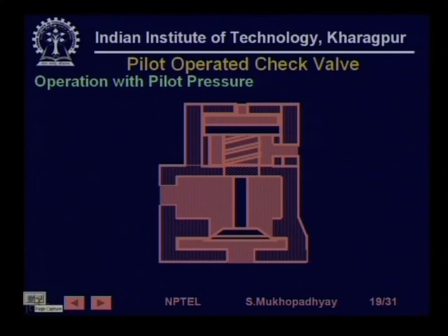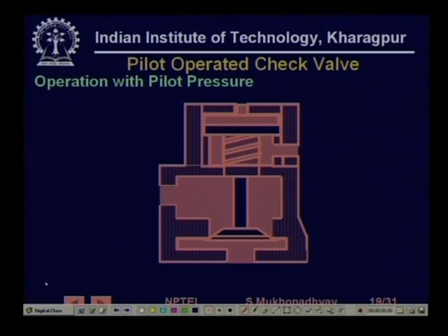When we have pilot pressure, this is the pilot port. So, you have pressure, this spring will be pressed and this will actually come out at the bottom, not exactly aligned, maybe somewhere over here. Now this opening is open, so the fluid will pass and can flow through these. If it opens, they can also get drained. So, this is a typical pilot operated check valve.